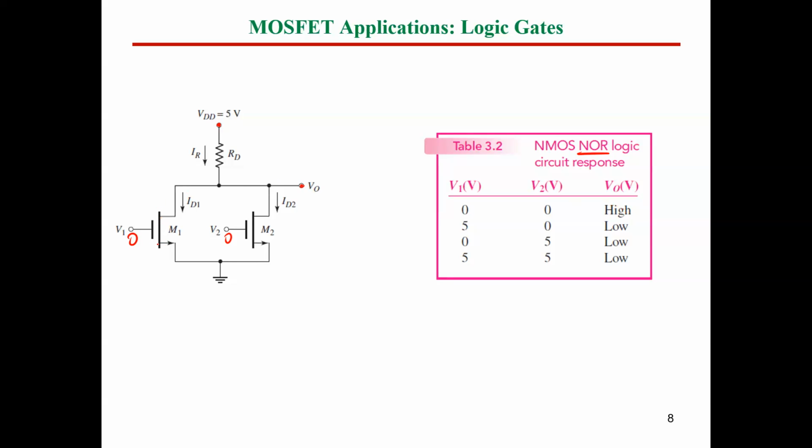If we apply active high here and active low on the other side, this means you would have a voltage that is going to turn on this transistor, and for sure you will have some voltage drop here, VDS. However, the voltage now, which is connected to V out, would be very small compared to the voltage VDD here.